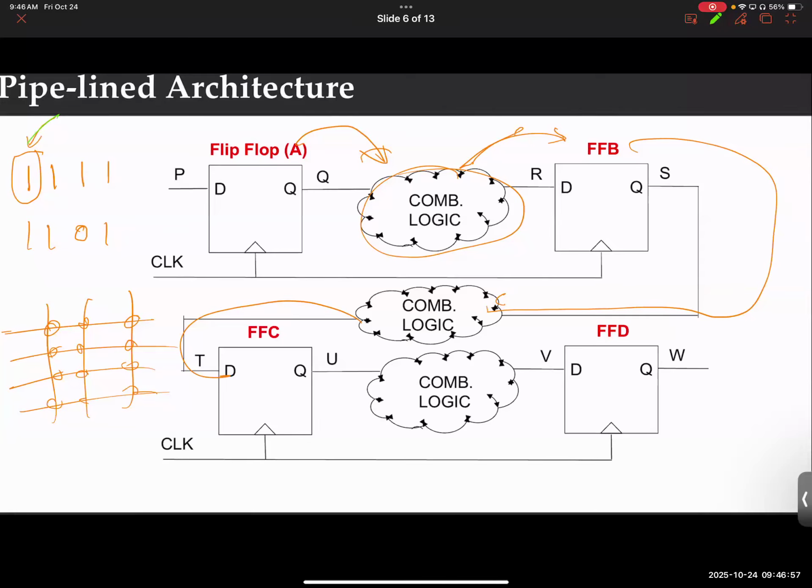Imagine that you are trying to use this bit to represent the row. You cannot use just one bit to represent the row, because you can only have two rows then, right? If you have 8 rows, you need 3 bits. You see my point here? So there are multiple bits dedicated to represent the row, and multiple bits dedicated to represent the column. Imagine the first 2 digits are used to represent the row, so that means you have 4 rows, and the second 2 digits are used to represent the column. So you know which row to go to and which column to go to, and then do something: read the memory, write the memory, whatever.